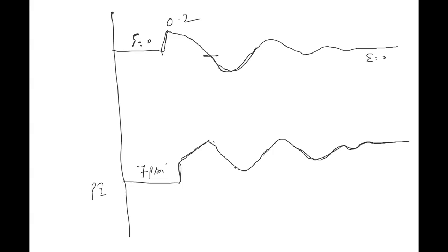Why this oscillation? Imagine a scenario where you are working as a PI controller. The moment you see the CSTR temperature is 59.8, you go and slowly close the control valve. Because it takes some time, no? When you change the valve, the temperature doesn't respond immediately. The cooling water has to flow through the control valve and affect the CSTR, so by that time you might have opened a little more. I have slowly opened, it has become 60, and it has become 60.2. Then you will slowly close, then slowly open, then slowly close, then slowly open. That means your hand is on the control valve till you see a temperature of 60 degrees. Are you understanding?